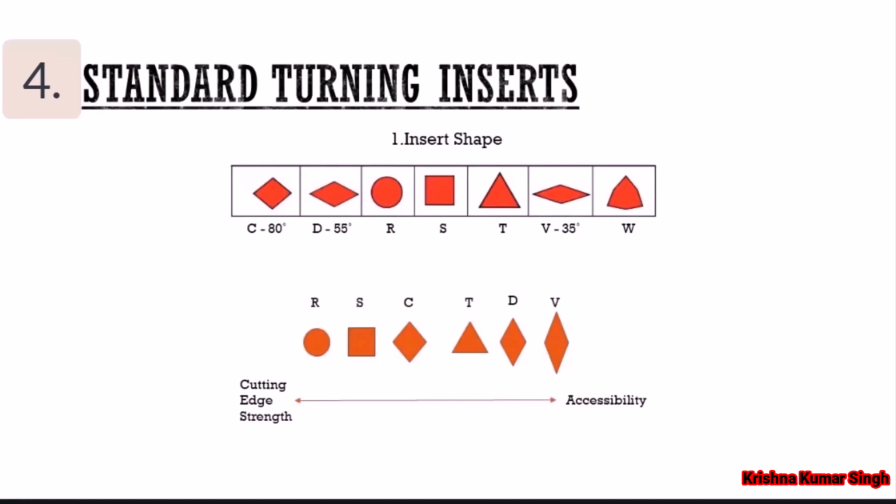The cutting forces in roughing operations are usually higher compared to finishing ones. On the other hand, a finishing operation usually follows roughing and is used to achieve the final geometry and surface finish. In interrupted cuts, the cutting tool engages and disengages with the material, like when trying to turn a square. In continuous cuts, the cutting tool is engaged with the material all the time, and cutting forces remain more consistent.